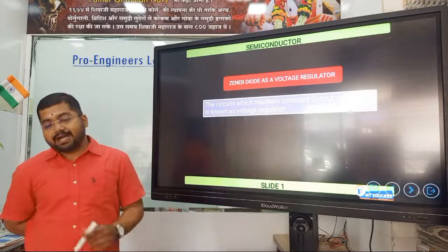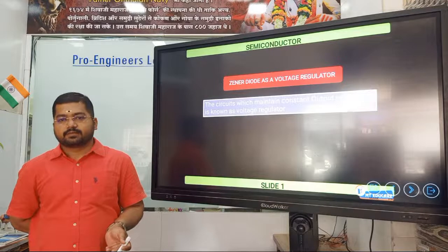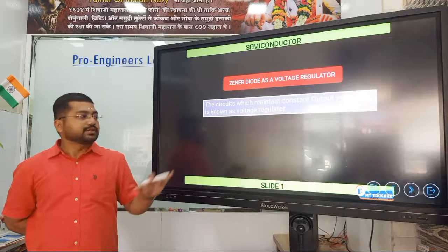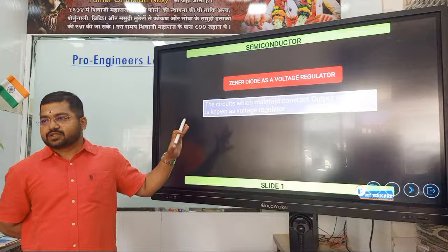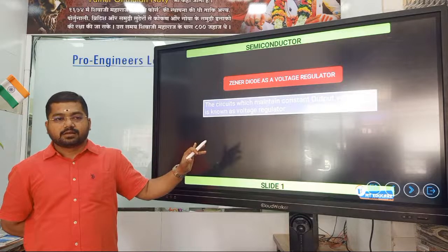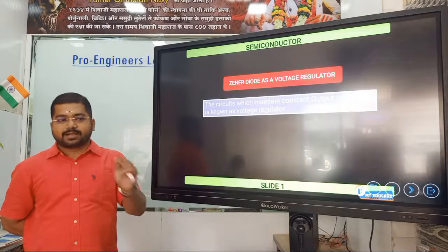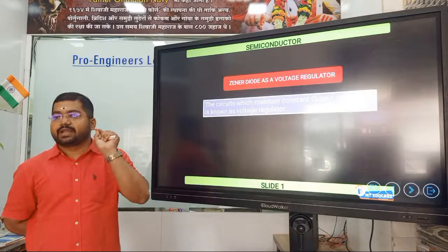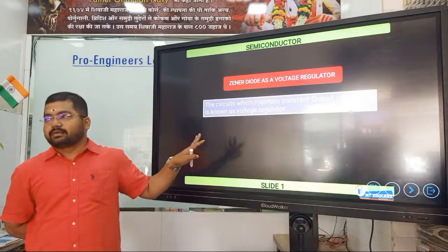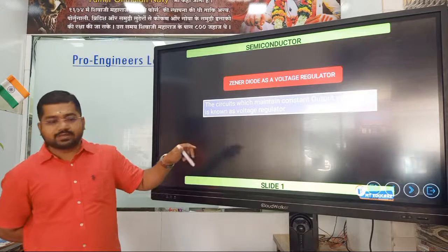But there might be fluctuation. Right? We never know. Because of that fluctuation, the devices may get damaged. So to prevent that, we have to use a Zener diode. So that simple small Zener diode plays a very important role to secure our electronic devices from damage.